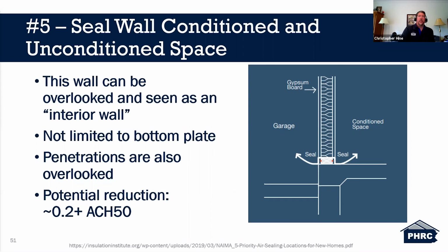is the wall from conditioned to unconditioned spaces, even though it may look like an interior wall. This wall could be between the house and the attached garage. This is not limited to what's being shown here, with it being limited to that bottom plate. It should be the whole wall that should be taken into consideration, but is often overlooked.